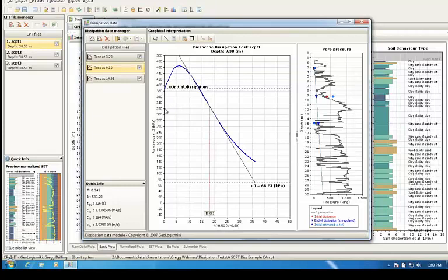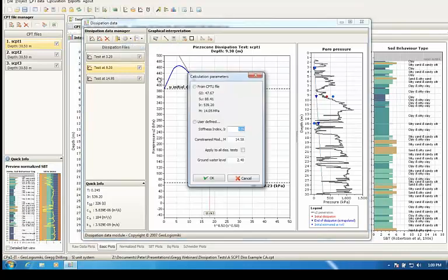So here's the square root time plot, and I'll just go up scale a little bit. So square root equal to 50, a little over 1,000 seconds. Now you can see a slightly easier curve to interpret, and the program has a system where you can draw a straight line portion to match the straight line portion. So you sort of try and line it up as best you can. Here I'm doing it rather quickly.